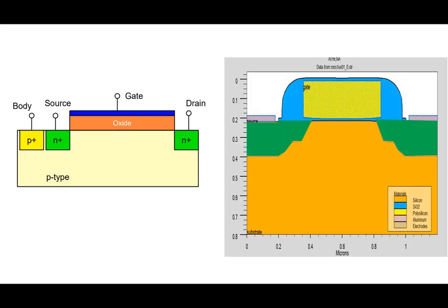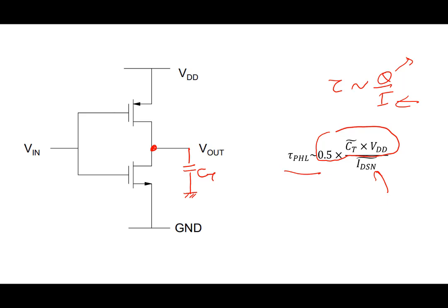Okay. So let's go forward and analyze this particular delay in a little bit more detail. One of the things you see in this expression, as we said, the drain current is a little bit easier to understand, which we all know: mu C oxide prime (VGS minus VT) square by 2. All of you know this expression in the saturation region. So that is straightforward. So let's try and understand a little bit about the capacitance at this particular node. For that we have to look at the transistor structure.